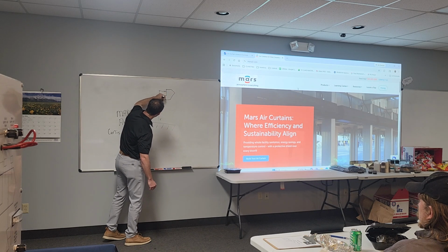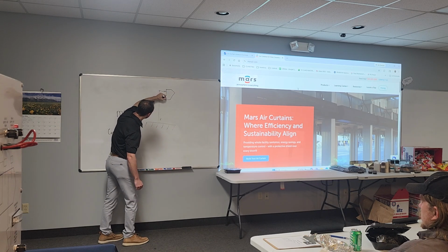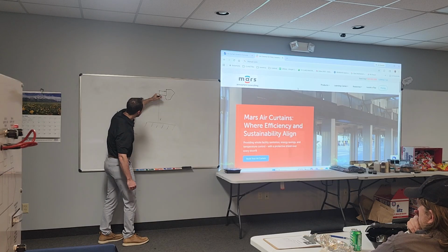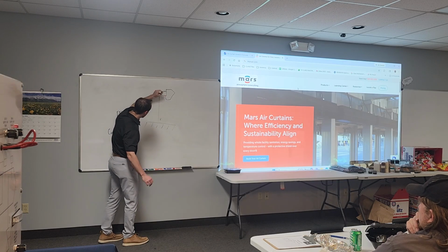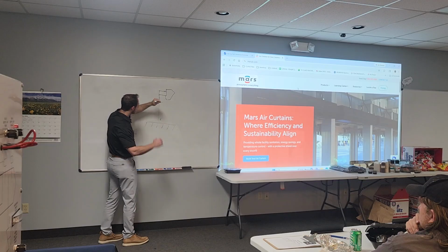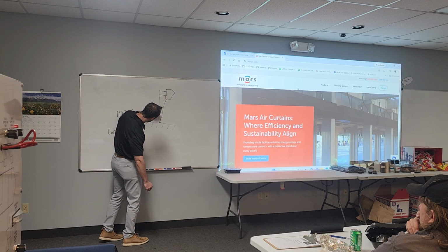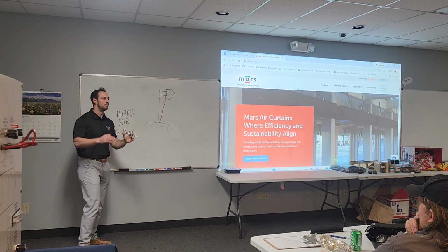Oof, gotta work on that. So this is the discharge. You just imagine that's a little discharge slot coming out from the bottom. You want to do the best you can to angle the discharge vanes so the air is flowing as close as it can to pretty much the middle of the threshold.